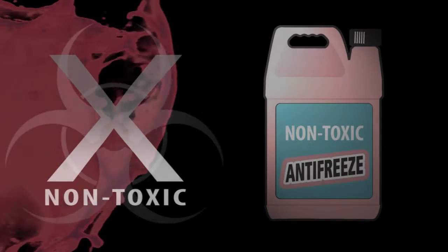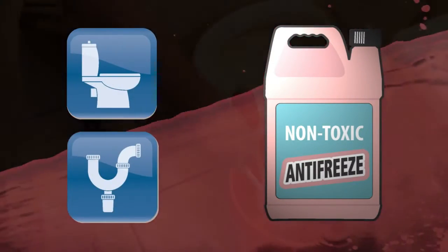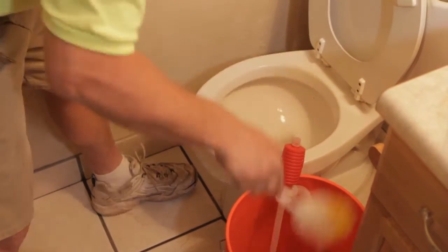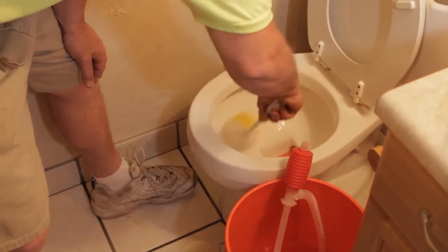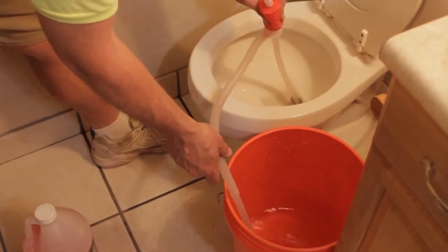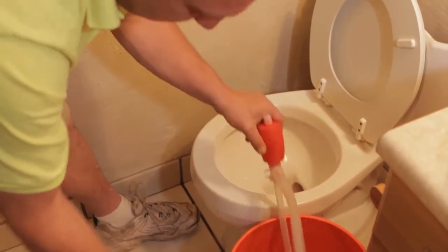The next step in a winterization is to add antifreeze to all toilets and drains. Toilets must first be cleaned. For presale properties, toilets need to be clear of feces and urine. Once cleaned, you will need to remove the water in the tank and bowl. For best practices, use a hand siphon or wet vac.